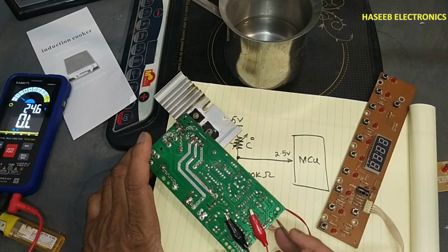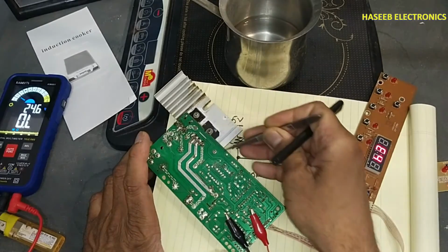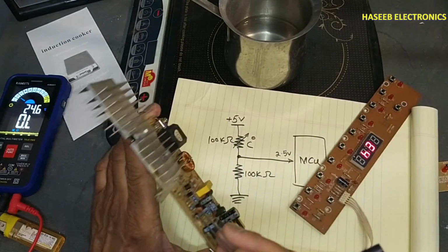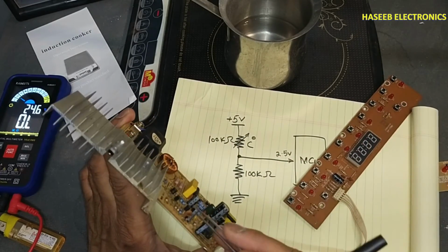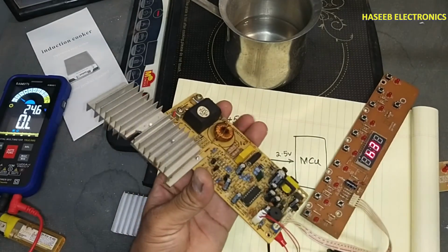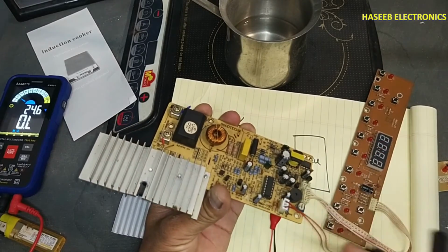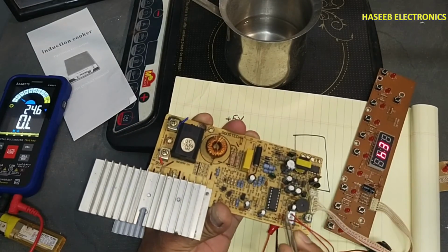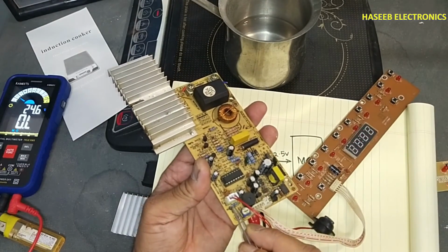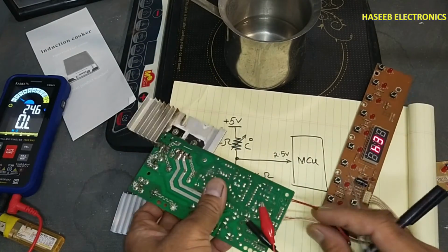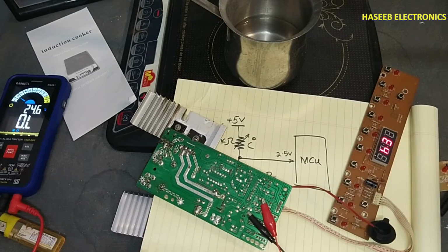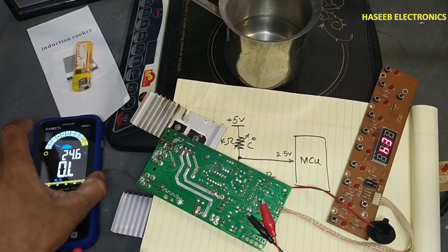The same working style is here. One line is going to one end of this sensor, and the second side is coming to this point, that is here. Here is a 20 kilo ohm resistance at this point and this capacitor. These are involved in this code. With this sensor we have one capacitor here, one resistor, that is here, 100 kilo ohm, and this capacitor. So we can check these components and we can check continuity. We can also verify the voltage on these sensors.